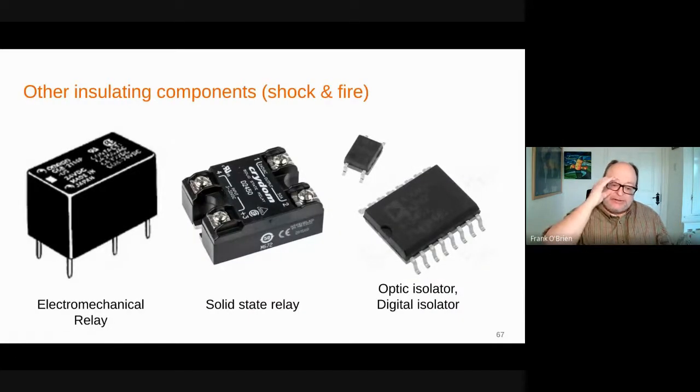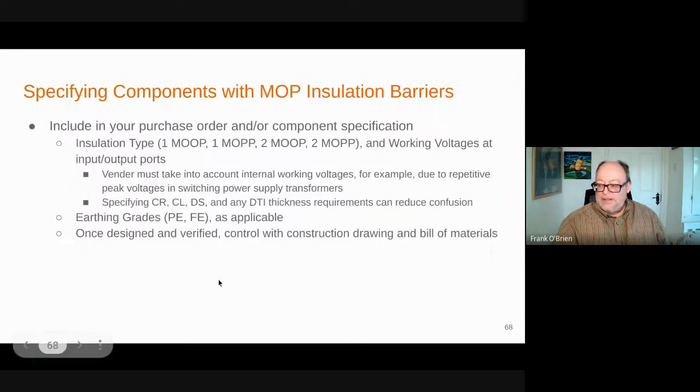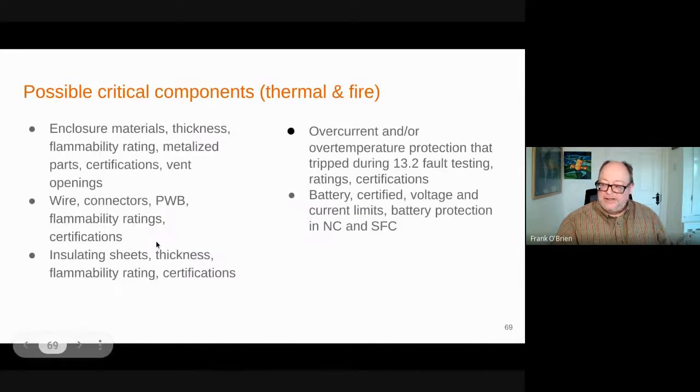Relays, optocouplers, high-speed USB: you're looking at magnetic or whatever magic is used to provide isolation at high data transfer speeds. There are old-fashioned relays with a switch gap, and solid-state relays, but in any case there's separation, and those should comply with appropriate component standards. Then just make sure it's consistent with your insulation diagram.